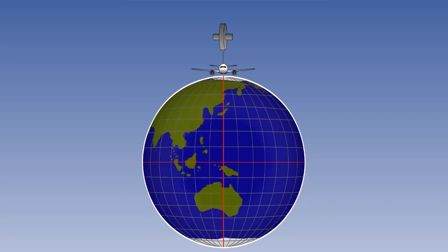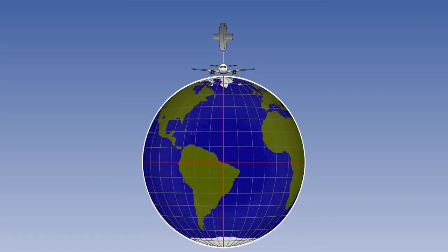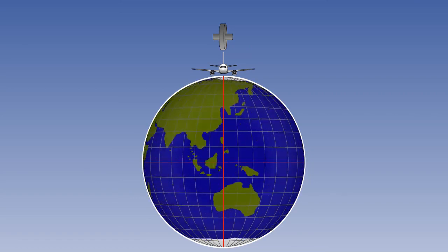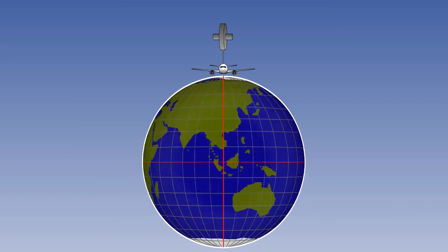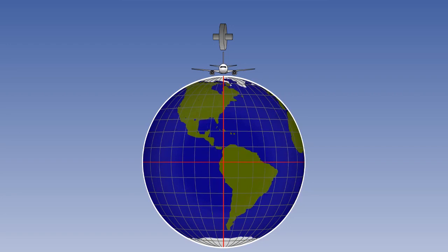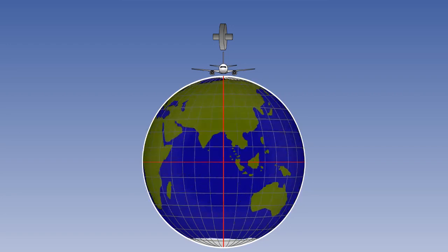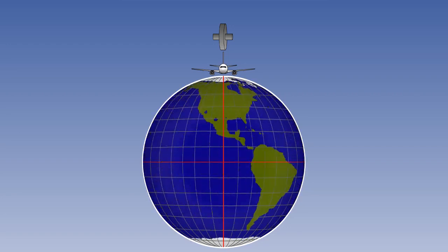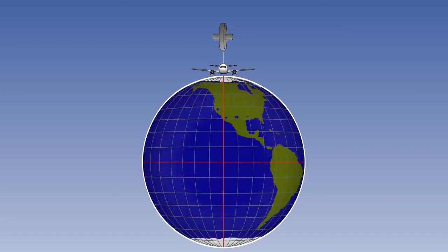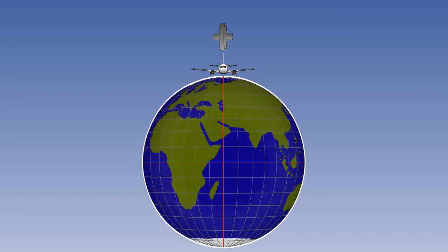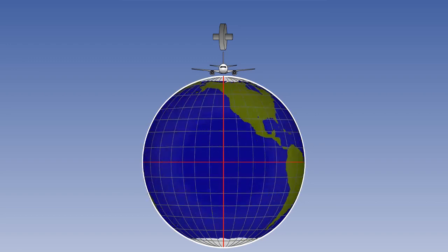Now the aircraft is at the North Pole, or latitude 90, and we are looking at the Earth from sideways on. As before, the wings are level, and the gyro axis defines the horizontal, or wings level. In this case, no matter what the rotation of the Earth, there will be no change in indicated bank angle. Earth rotation will give apparent yaw but no apparent bank.